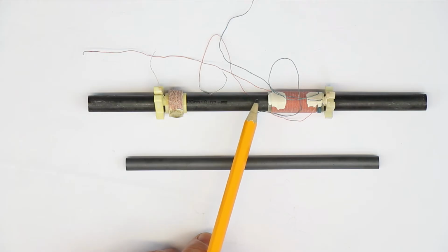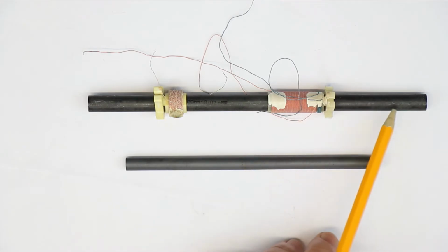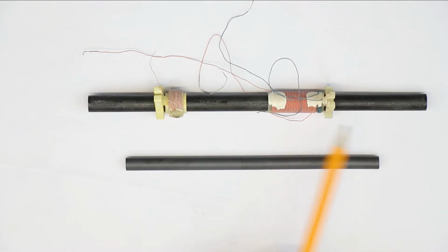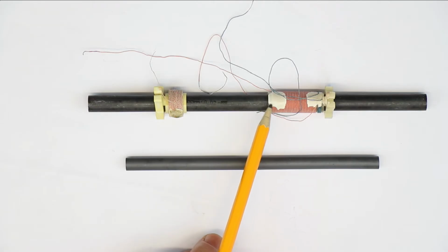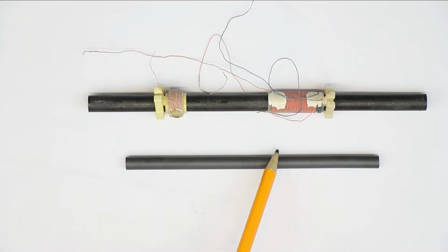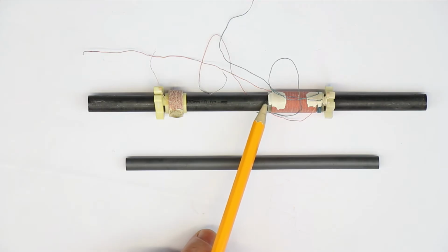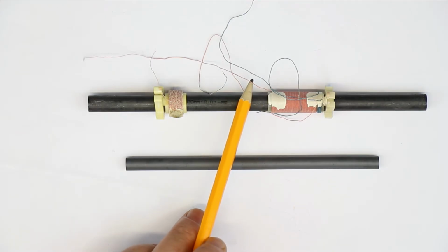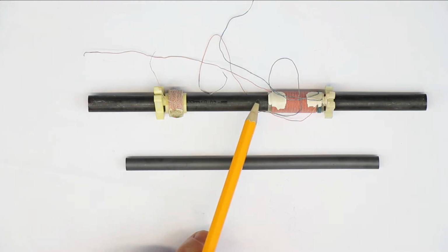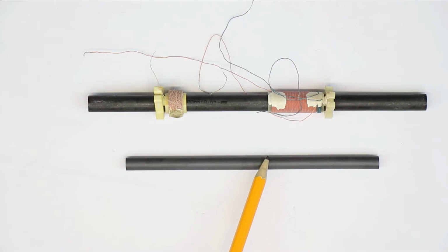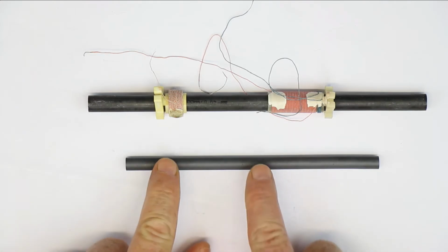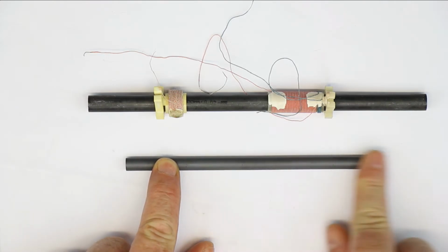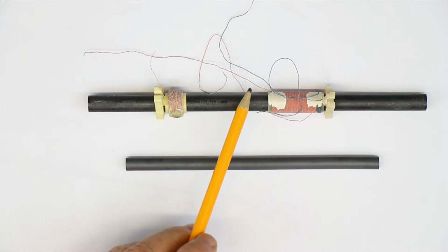You get the largest inductance when you place the coil in the middle, and you get an increasingly smaller inductance when you shift the coil to the side. The second thing is the protection of both the ferrite material and the Litz wire, or whatever kind of wire you use, because ferrite material is not only very brittle, it cracks immediately if you let it fall on the floor, but there can also be some very sharp edges, and that would break